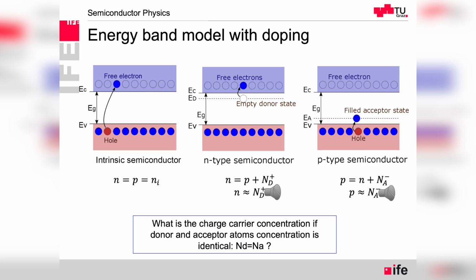These are so very close to the respective bands that, as you will see in one of the slides, I have tables where the energy is listed for the dopants, how much energy we need to give to the charge carrier so that it moves to the valence or conduction band. At very low temperatures the doping is already working. This is related to the freeze-out temperature. We go out of the freeze-out and these dopant charge carriers are available for conduction.